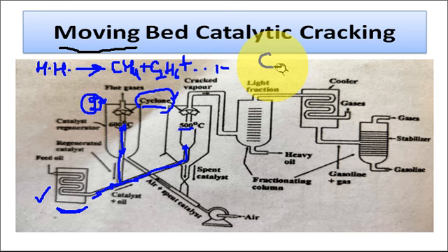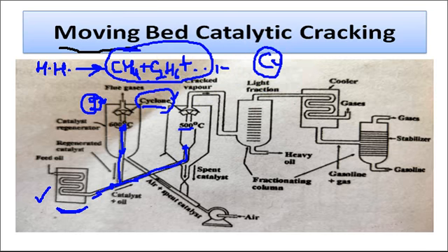So look at here, due to the high temperature, all the hydrocarbons are in the vapor phase while carbon is in the solid phase. This is the solid while all these are in the vapor phase. So these are called the cracked vapors while the carbon particles are in the solid form. Look at here. Here is the cyclone present. So when the cyclone moves, all the gases, due to their lighter weight, come in the central part and move from this direction, all the cracked vapors, while the carbon particles move towards the walls of the reaction chamber.